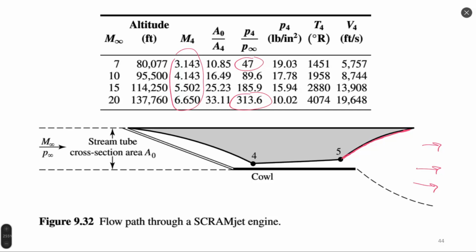mechanically resistant, and then when we look also at temperature, it's not in centigrade, but still very high temperature. It must be resistant to thermal loads and pressure loads as well. So highly resistant, thermally resistant materials and strong materials must be used for construction of the combustion chamber, and such two limitations of temperature and pressure create huge difficulties in construction of such flight vehicles.